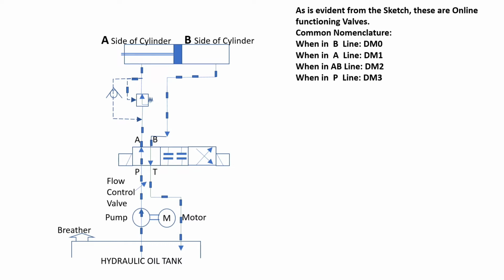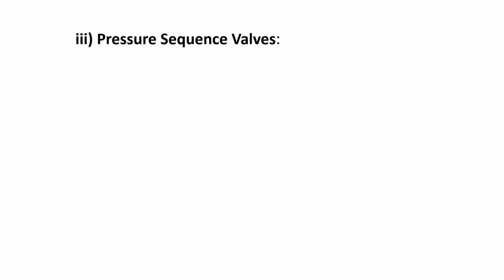That means the P to A oil galleries are connected through the valve's spool that is inside the valve main bore. So as you can see, when the pressure is high and you want to reduce the pressure, the spool inside the valve moves and reduces the opening, like in any common tap. So that will help less oil with less pressure to go to the cylinder. You can see.